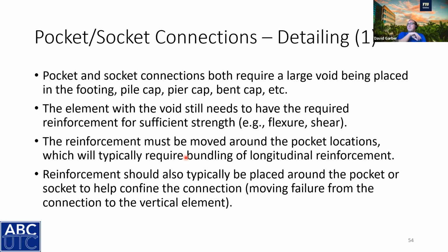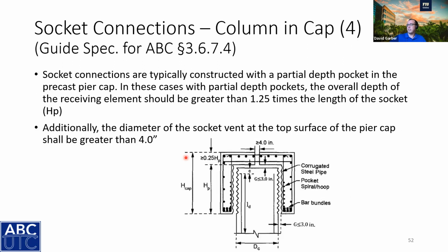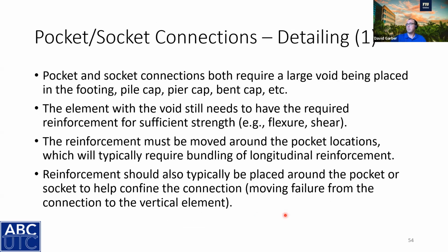So in terms of detailing, pocket and socket connections can create a little bit of a challenge. With the pocket or socket, you still need the reinforcement that you need in the cap, but you need to somehow move it into portions that are precast. So this can lead to bar bundling and a large amount of reinforcement immediately adjacent to the pocket. So that can be one of the detailing challenges.